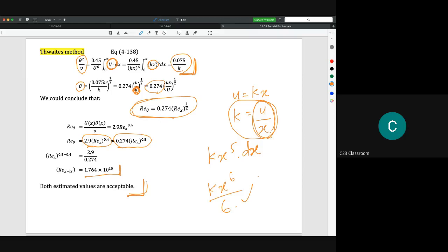The reason why you will find that there are a lot of equations in our textbook is because turbulence is actually still under research. So there is no single equation that could solve turbulent boundary layer problems. Another reason is that the turbulent boundary layer is a chaotic motion, a chaotic behavior.